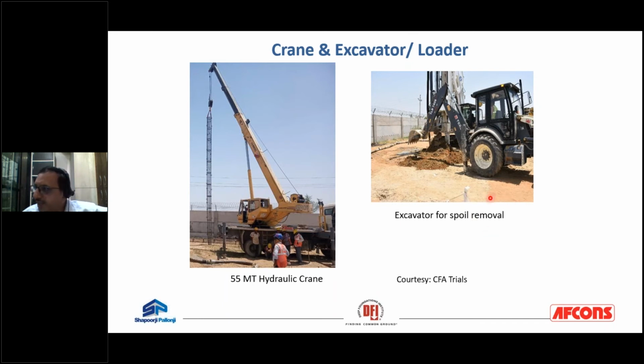Removal of spoil is very important as a housekeeping, and the place around the piling should be clean and it should be devoid of any such excess mud. So your mobile excavator should always be ready to remove any muck that is being collected by the auger.